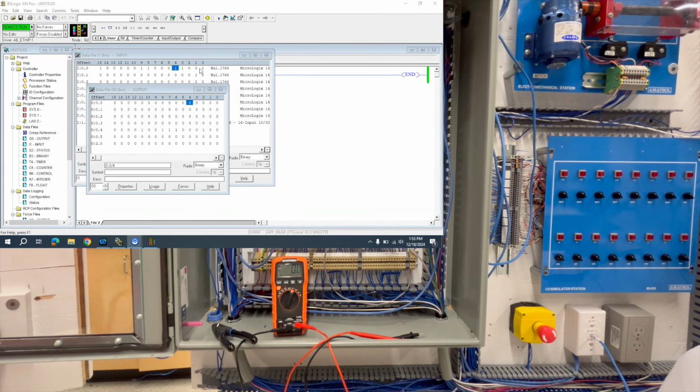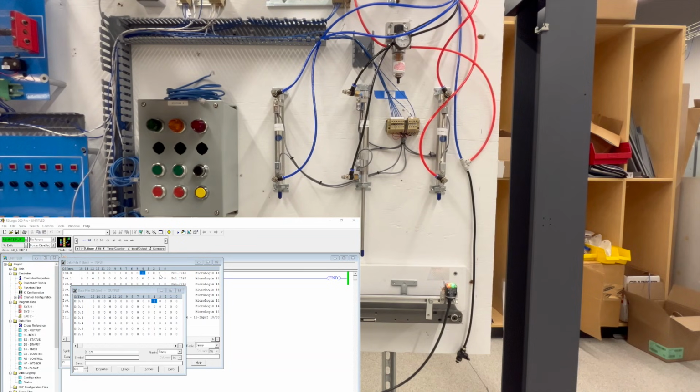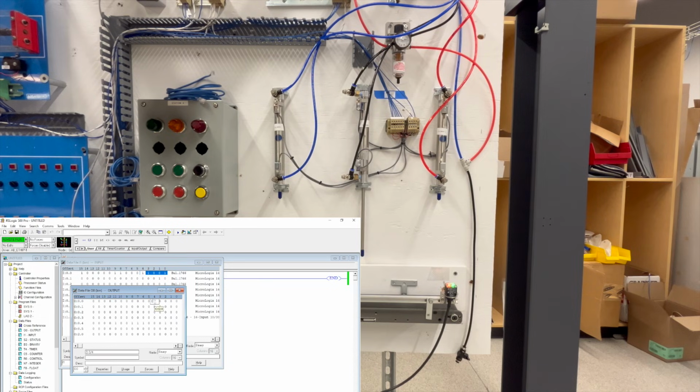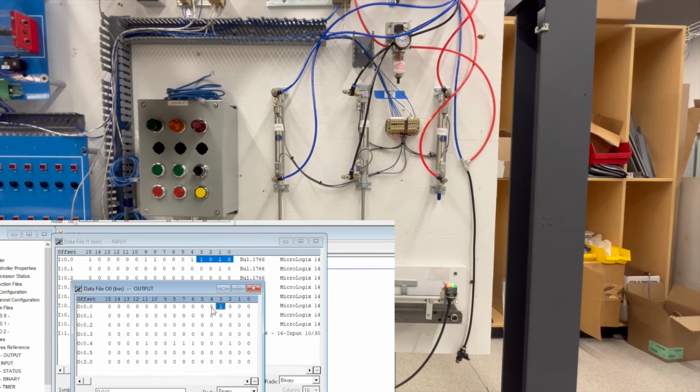And you can see here on the inputs that these are now working. So I can come over to here. I'm going to activate the outputs and make sure that they are all changing. But I can see here on my screen, I'll highlight the 4 that weren't working. 2 of them are already working, but let's just double check. Okay, and 0 and 1 changed places. Come in here. Retract the cylinder, 3 came off, 1 came on. Now I know that my inputs are working and that was the problem.